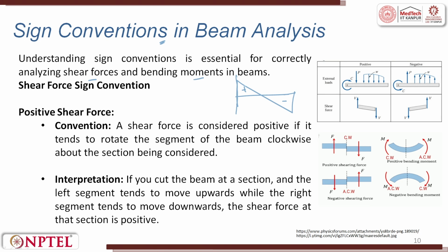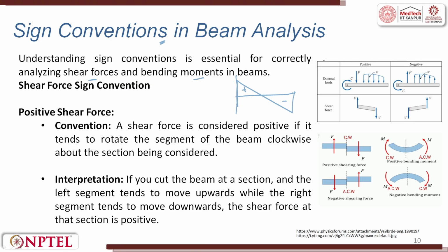And second thing, whatever convention you follow, it has to be uniform during the complete process. For example, if you take counterclockwise as positive, then all along you should have counterclockwise positive. If you have it clockwise, you keep it clockwise. But there is a sign convention which is followed, and I would request you to follow it. And when it is a simple structure, you will have only a varying distributed load, or only point loads at the extreme ends, right.